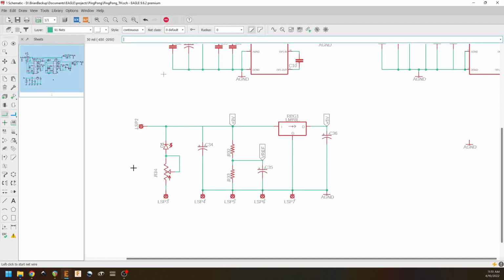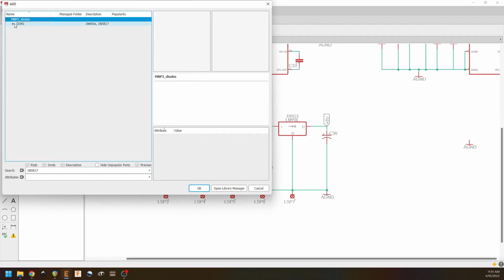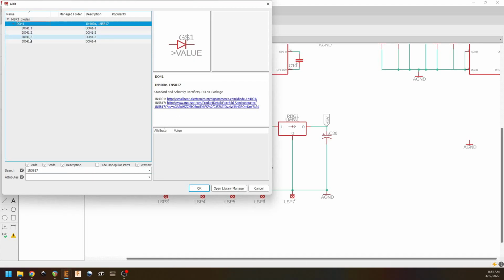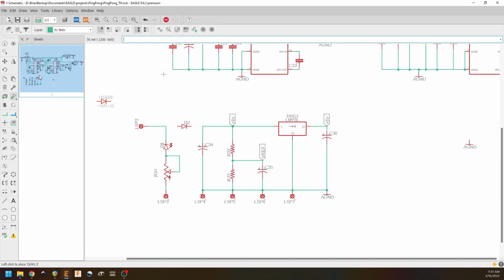And now we need some reverse polarity protection. So I'm actually going to break up this right here. And I am going to look for a 1N5817 Schottky barrier diode, because it has a very low forward voltage drop, about 1/4 volt, and if reverse polarity stuff gets connected up, this guy will blow and it won't affect anything downstream.